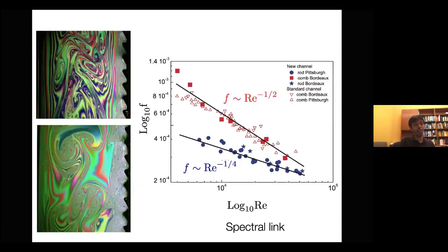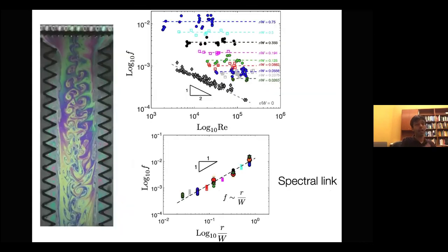That led us to explore friction in 2-dimensional flows. For smooth walls, we were able to show that Enstrophy cascade gives a new Blasius scaling, and inverse energy cascade gives the same scaling as in a 3-dimensional flow. And for rough walls with Enstrophy cascade, we were able to verify a new scaling for the Strickler regime.